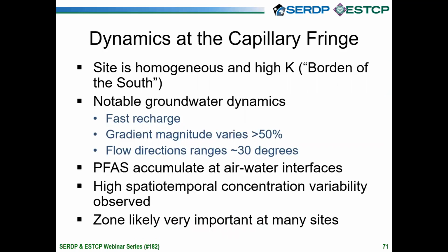So a quick side note here. Remember that I mentioned a couple of times the site is very homogeneous and highly permeable. In fact, our team refers to this site as the Borden Aquifer of the South. However, the groundwater dynamics are quite notable. There's very fast recharge. The gradient magnitude varies by more than 50% over the year, and flow direction changes more than 30 degrees. And as many of you know, PFAS accumulate at air-water interfaces, and therefore we can expect complex behavior in a dynamic setting like this.